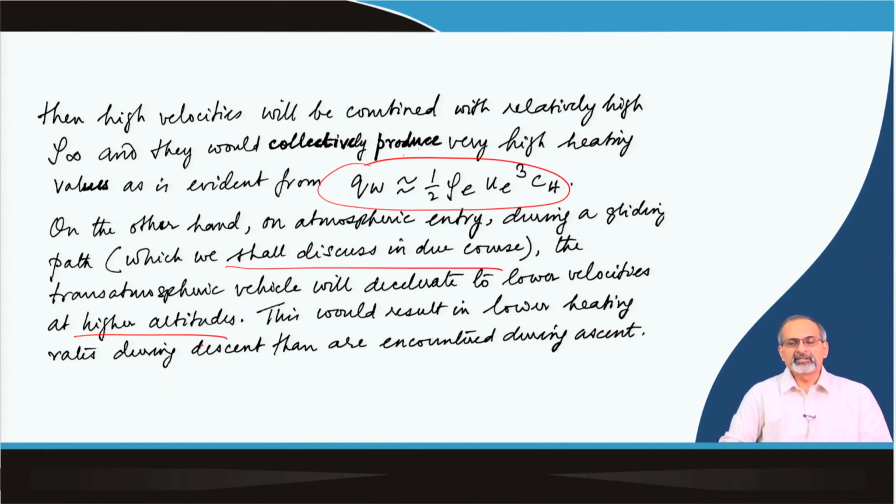Therefore, when we talk about viscous flows past high speed vehicles in hypersonic ascent or entry, we have to talk about the effect of the different transport phenomena and the role that they play in the aerodynamic heating of the vehicle. When we account for those effects realistically through solution of the compressible Navier-Stokes equations along with accompanying equations to model the chemistry, then we will have a much more realistic assessment of the aerodynamic heating.